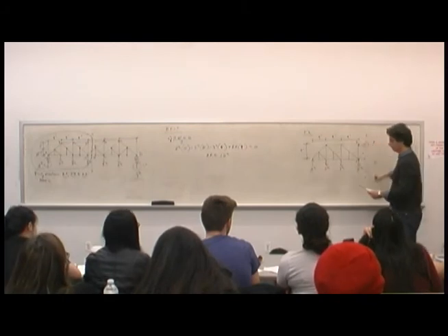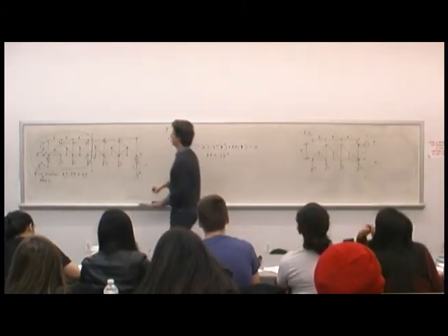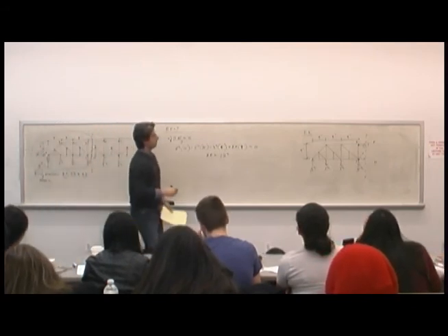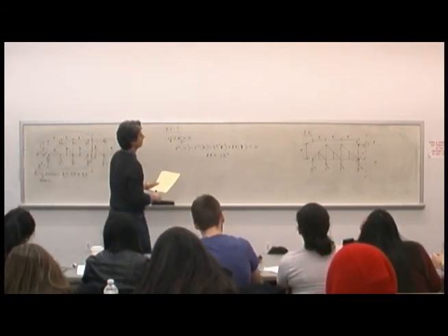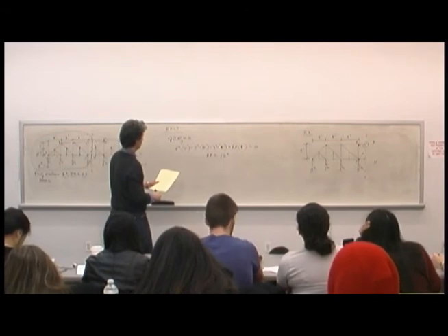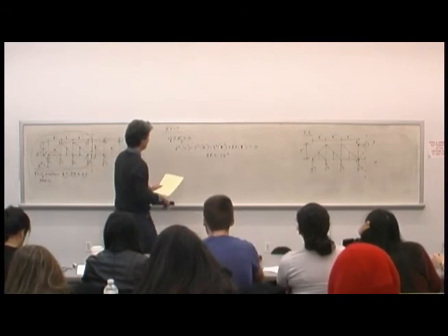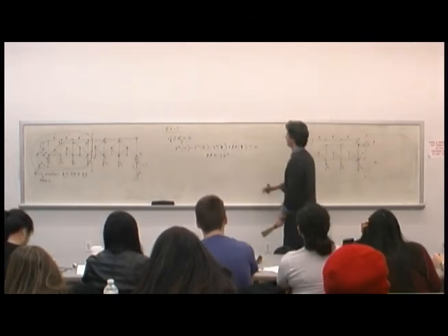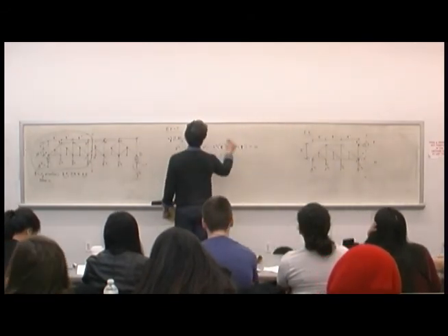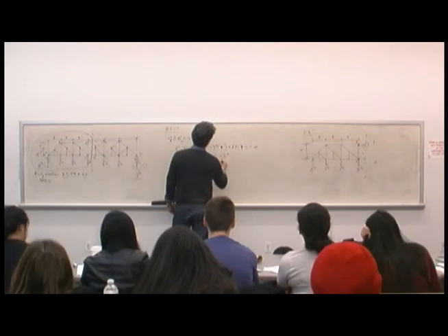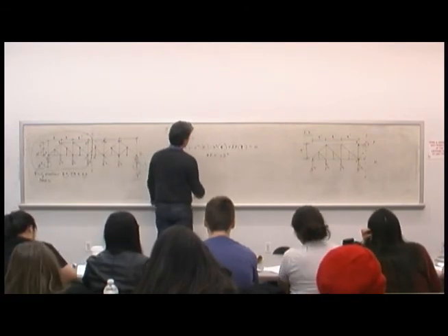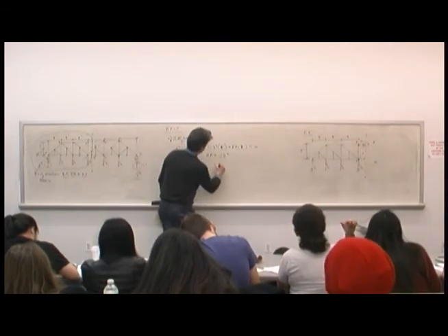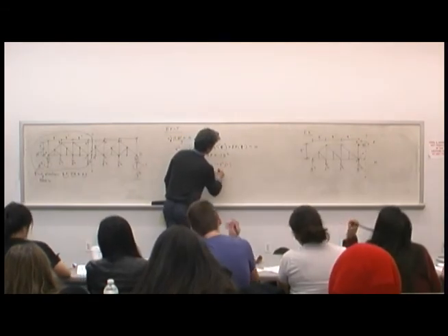Pulling, right? So EF is going to be in tension, right? Is that right? Oh wait, it's negative, isn't it? It's negative 17 EF. So what happens? This is going the other way, right? So now EF is equal to 17 kips in compression.